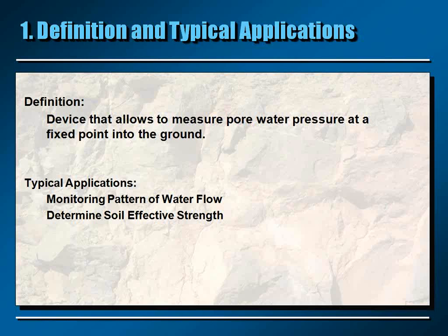The typical applications can be divided in two. The first one is when we are interested in monitoring a pattern of water flow. A typical example of that is dam monitoring. It is common to install piezometers in the dam and in the dam foundation to determine the water flow through the dam and below it, to validate that the dam is behaving in a proper way.